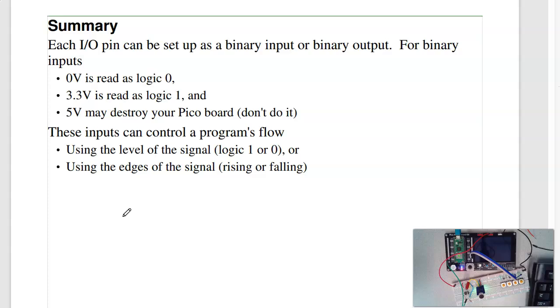And one thing to note, what we're doing is a little bit inefficient. I'm using up the I/O pins. That's not necessarily bad because you only get so many I/O pins. If I don't use them, I don't get any money back. But I can use up the I/O pins pretty quickly. There are other ways to do I/O. I can do serial I/O. With only 3 I/O pins, I can control an unlimited number of devices. That'll be our next lecture. But anyway, that's lecture number 6 for ECE476.